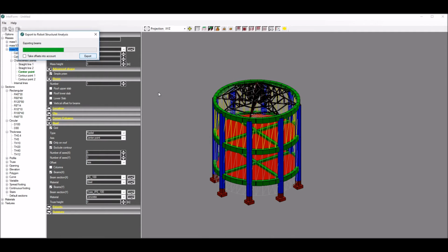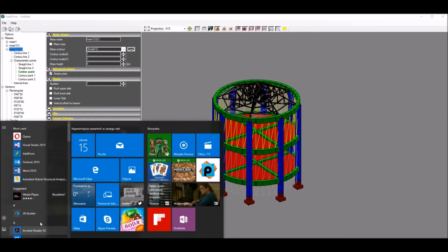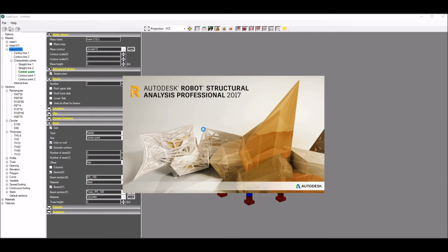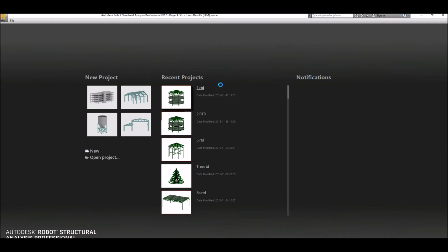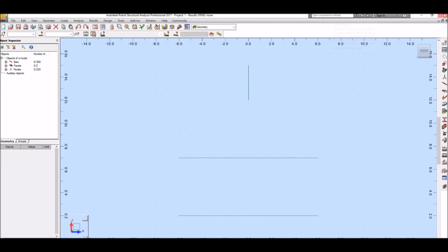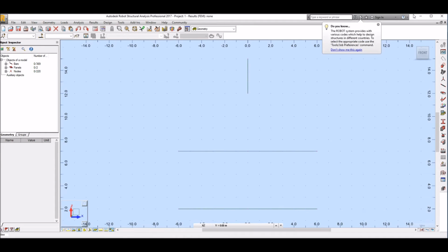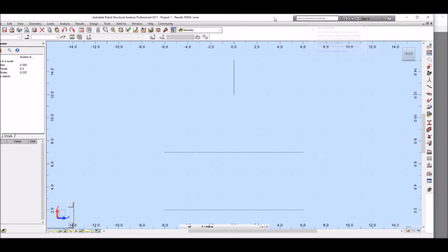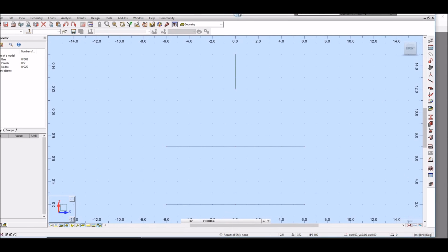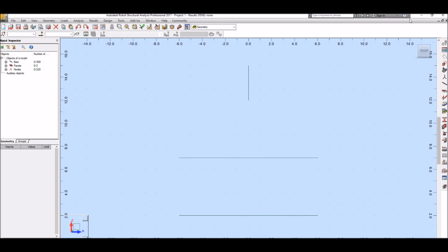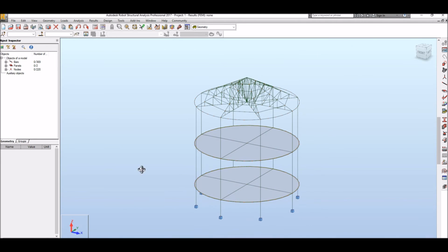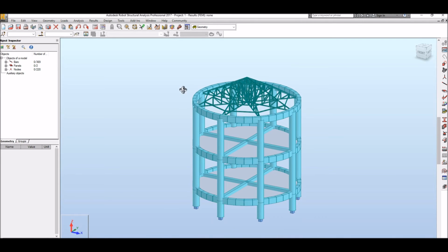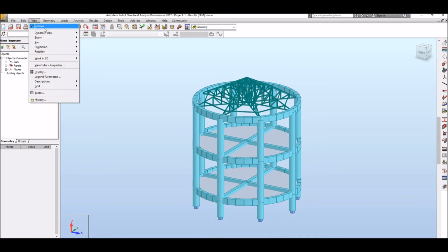IgentForm supports also other formats like DXF, IFC and OBJ. Thanks to it, model created in IgentForm can be easily exchanged with other commonly used programs. Model exported in RTD format is calculation model, so after opening it in Autodesk Robot Structural Analysis, it is generally ready for calculations. Now in RSA, I change display mode for sections and make a verification of model correctness.